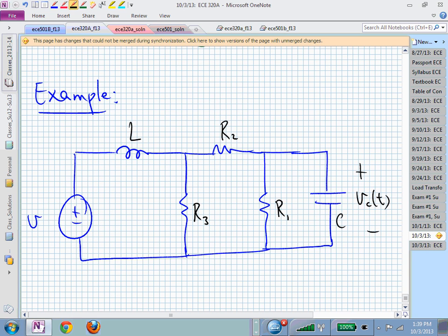Picture a ladder on its side, and now you have the rungs that are these vertical. There's a capacitor, a resistor. What we're going to do is climb that ladder from the output towards the source, towards the left. We're going to go up the rungs of that ladder. And what we're going to try to avoid is writing three coupled mesh equations, for example, which could get ugly. Then we would just turn the crank and get an answer, and we'd go, I don't know if that's right or not. I may have made a mistake. But the ladder technique allows you to sort of follow your work as you go.